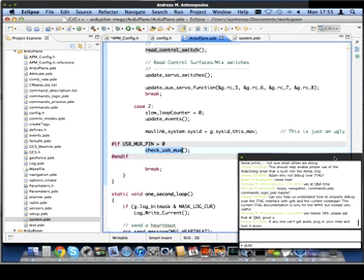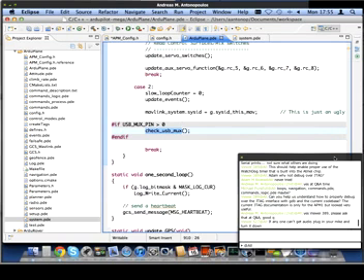It also checks the little thing down the bottom there. It's quite interesting, the check USB mux. That's what supports automatically switching between the USB connected telemetry versus the radio connected telemetry on the APM2. There's a little hardware mux that switches the serial port, the UART, between the USB connector and the telemetry connector, and it's going and checking a pin set by the 32U coprocessor.